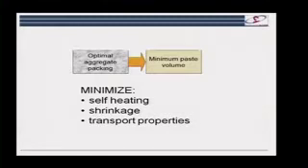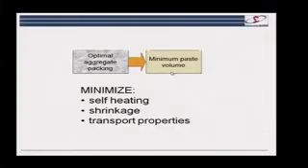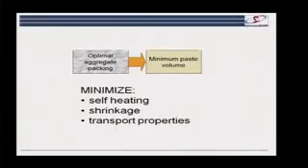So we want to have that good gradation of aggregates, because if we have that good gradation, the optimal aggregate packing, we can minimize the amount of paste, and if we minimize the amount of paste, we optimize a lot of other properties. The paste, when it reacts, as we're going to see later, emits a lot of heat.